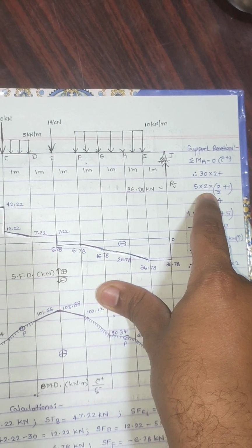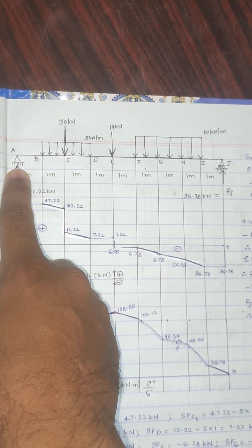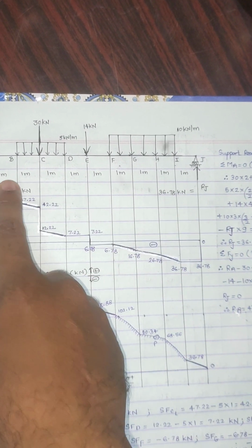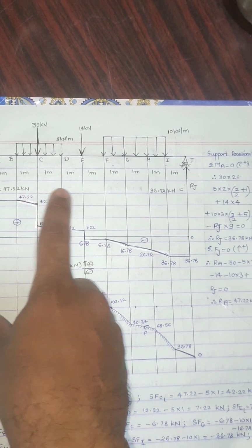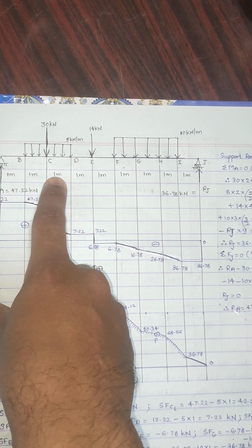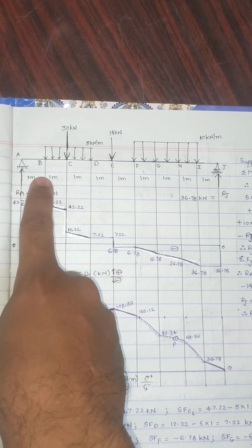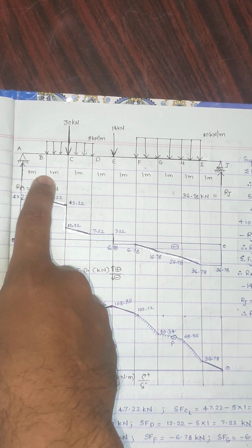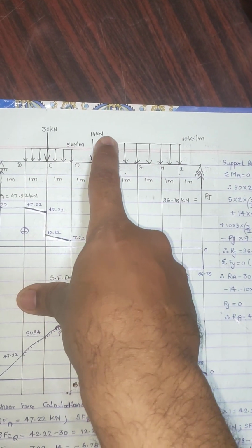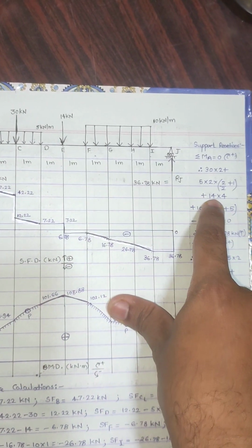So 5 into 2. Now if the UDL is not extended from point B to point A, what you have to consider is, 5 into 2 is the length of the span, and for the centroidal distance in bracket we have to put 1 plus 1, 2, divided by 2, that is half of this distance, so 2 by 2, plus from point B to point A the distance is 1 meter, so 2 by 2 plus 1,